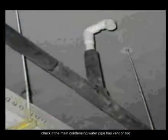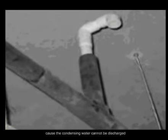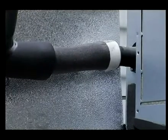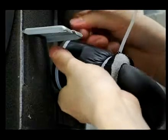Check if the main condensing water pipe has a vent or not. Check whether the main discharge water pipe is jammed, which causes the condensing water to not be discharged. If there are any of the above problems, they can lead to water leakage of the indoor unit. Please modify it according to the requirements of the technical manual.